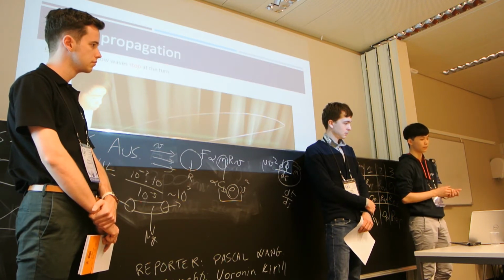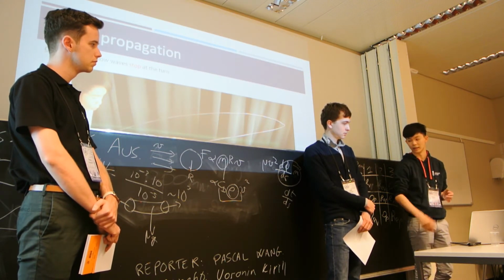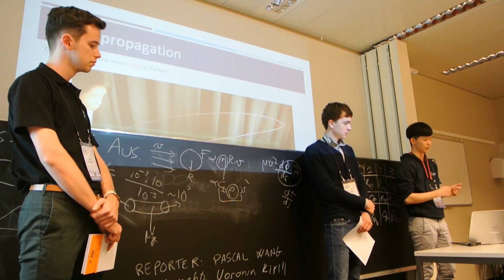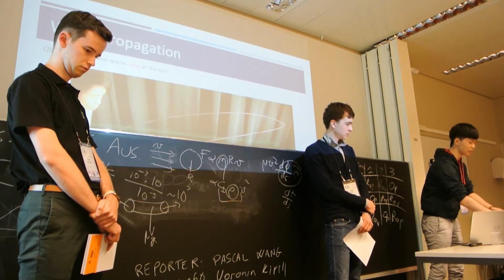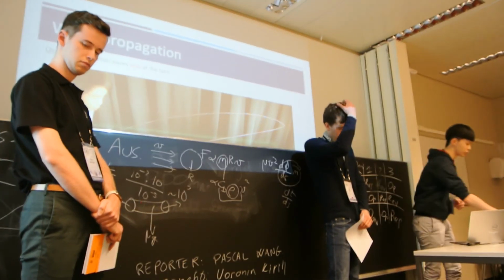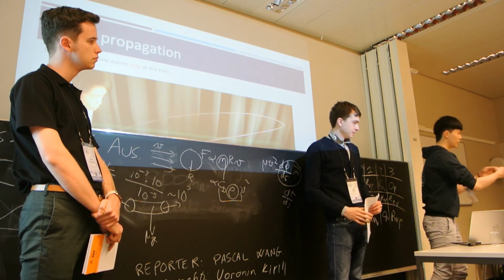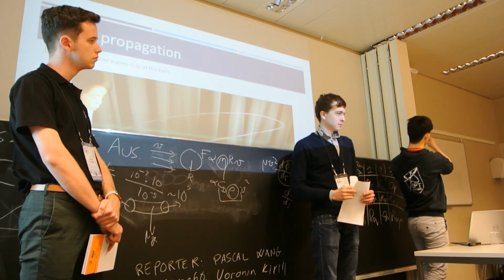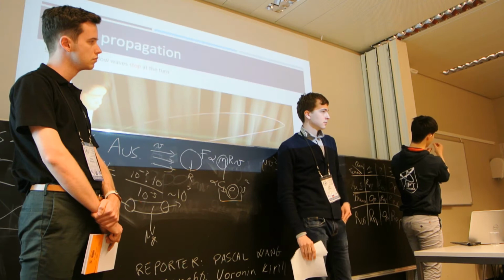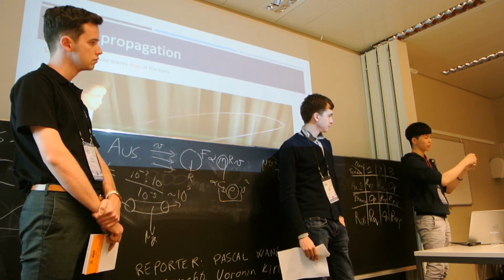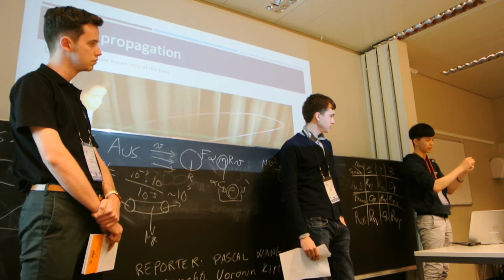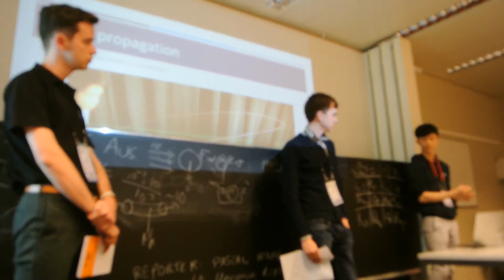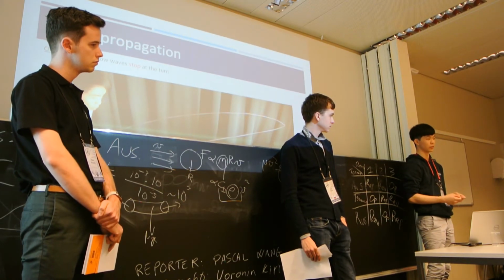When the speed is too high, the tension between the two wheels at the entrance can be negative. This means that the string is pushed around itself. It is not under stress like this, but is pushed like this, and so we do not get a stable shape.